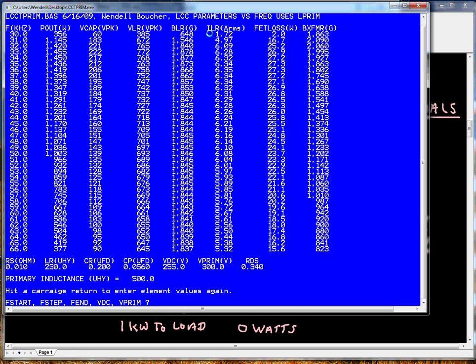This is the current passing through the series inductor and through the series capacitor as well. So at the high power, we see it's about 6.08 amperes RMS. We'll show that to you later also. Here's the FET loss for an RDS on of 0.34 ohms per FET. There's 4 of them in the bridge. Now we can reduce this number, of course, by reducing this number. And we could have done that, but I wanted to show it to you with a value that happens to be in the computer library already.